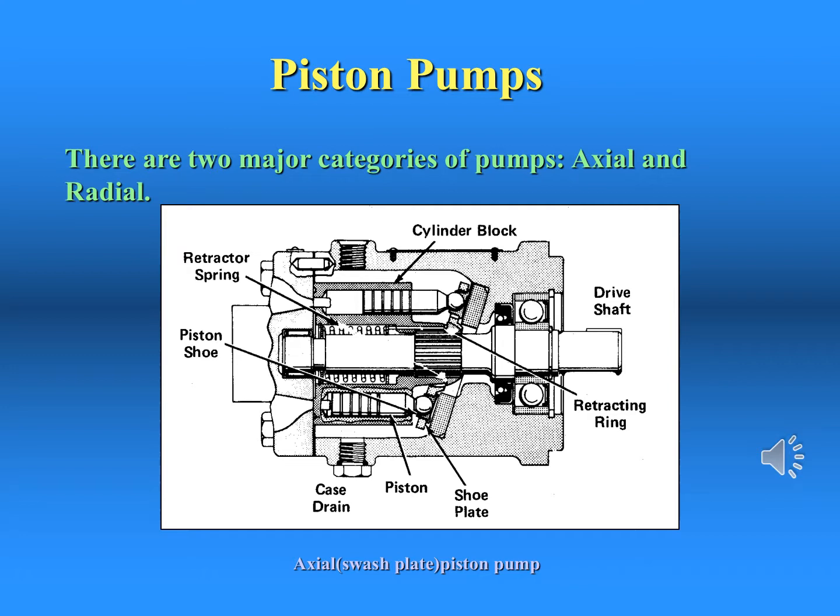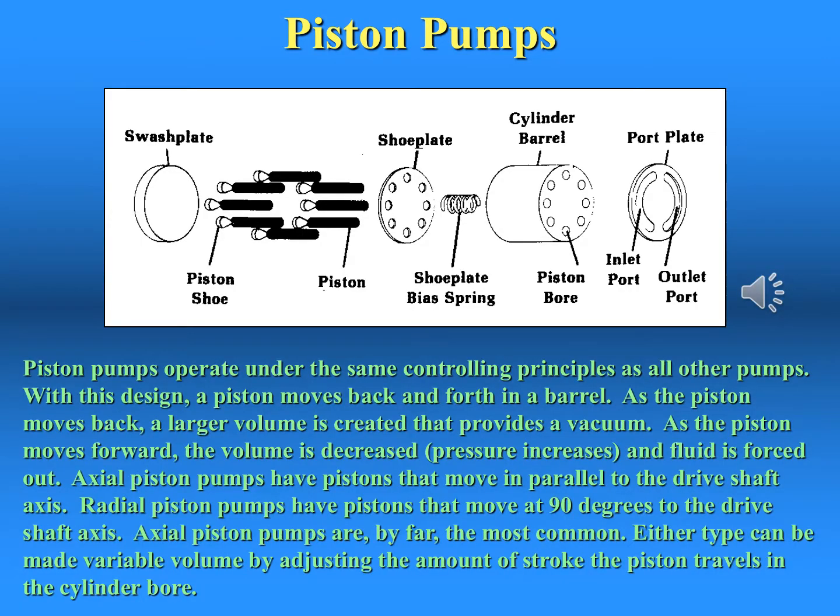The swash plate in this model is fixed and at set angle. The pump is fixed displacement. An exploded view of the internal group shows the pistons with shoes that slide on the swash plate. The shoe plate maintains contact between the piston shoes and the swash plate.